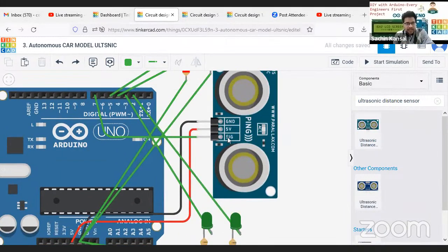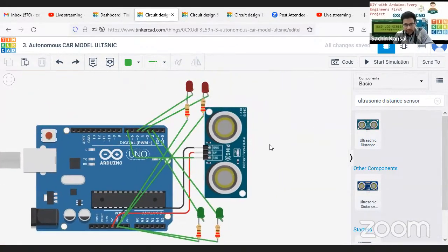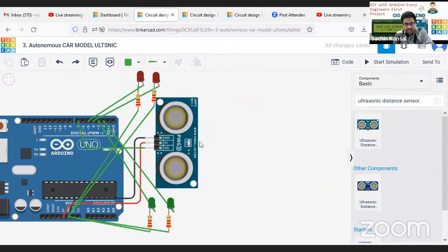This is a signal actually. This signal registers the distance between the object and the sensor, and you can write the value to port number 7. So ideally, what this layout will give you is, based on the distance between the sensor and the object, if it is coming too close towards the sensor, the red LED will glow, or let's say will be high. If the object is going far away from the sensor, based on some threshold, the green LED will glow. Just think of an example.